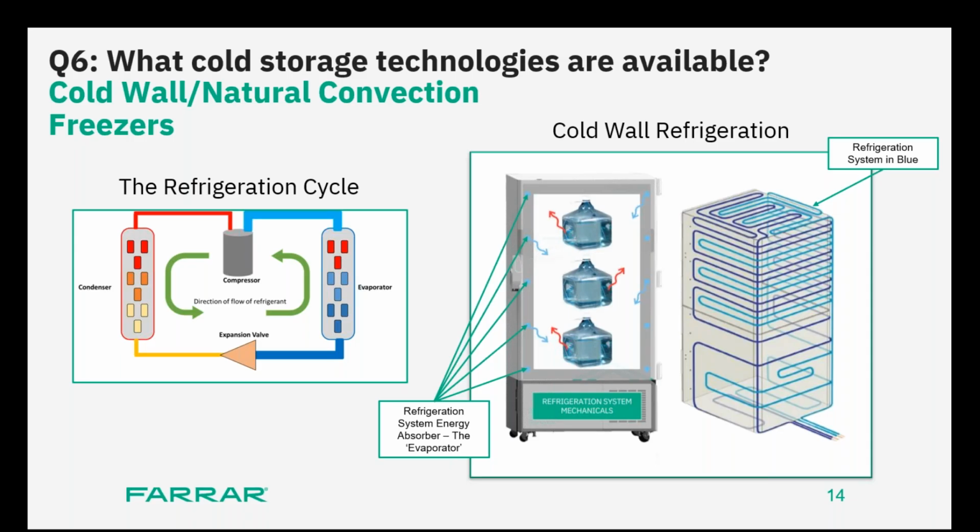which is one of the 2 heat exchangers. In this instance, you will be removing heat from the vapor. And what happens is that the surrounding medium, it could be either air or water, doesn't matter, would actually remove that heat, thereby making the vapor liquid. So what comes out of this condenser now is still that high pressure, but low temperature liquid. And then it goes through this expansion valve.